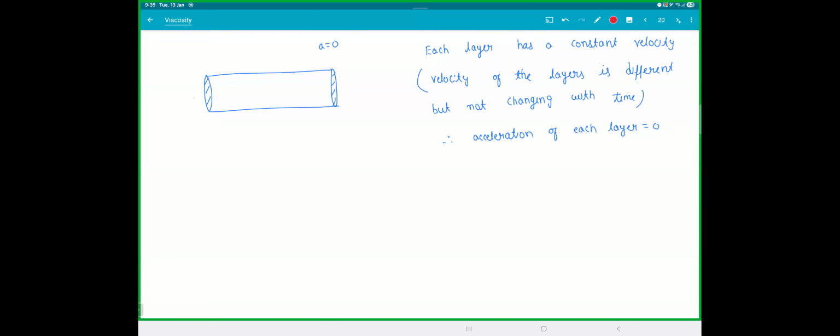That means from the left-hand side, the pressure is pushing P1 pi x square. From this side, it is pushing P2 pi x square. This difference in pressure must be balanced by the friction acting on this surface here. The friction is like this, F viscous.